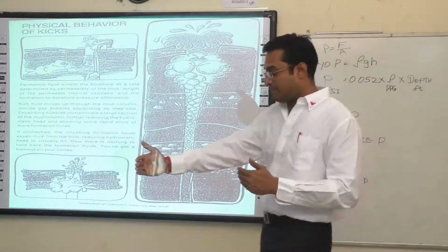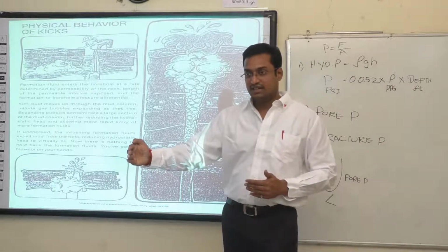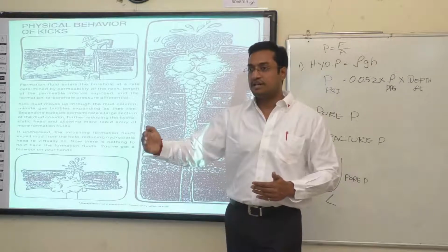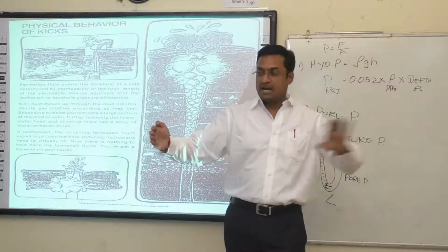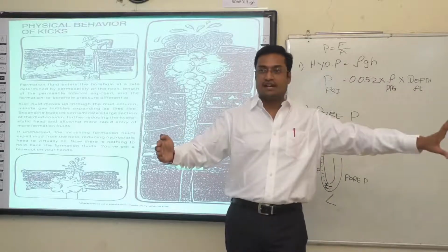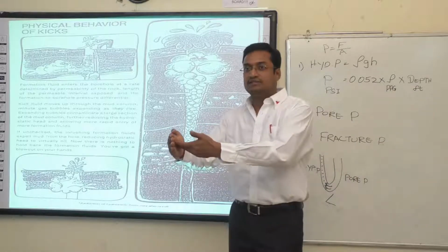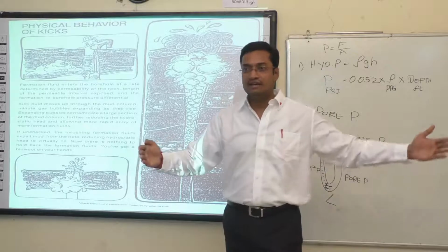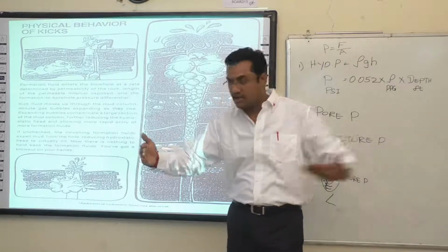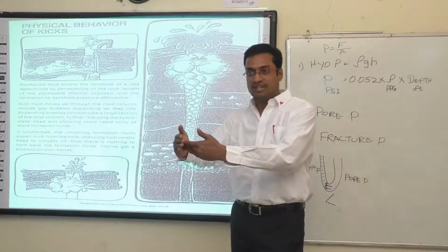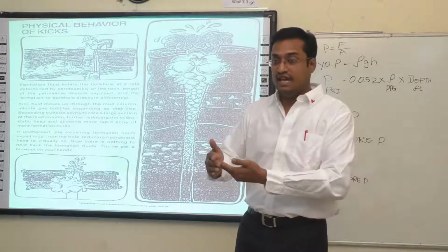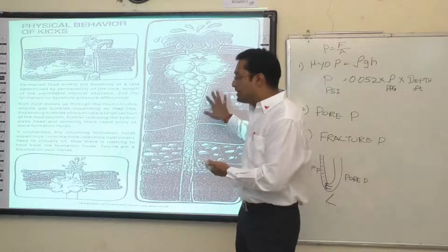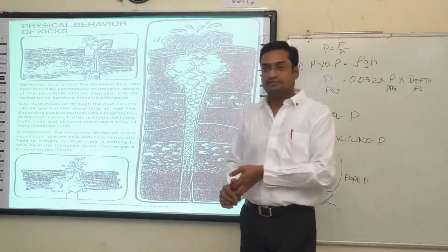So if a kick happens at this place and the permeability is very good, the whole formation at that depth keeps acting on it. Very quickly, everyone is alerted and fluids start rushing into the wellbore, if the permeability is good or high. Assume that the permeability of the rock is very bad.